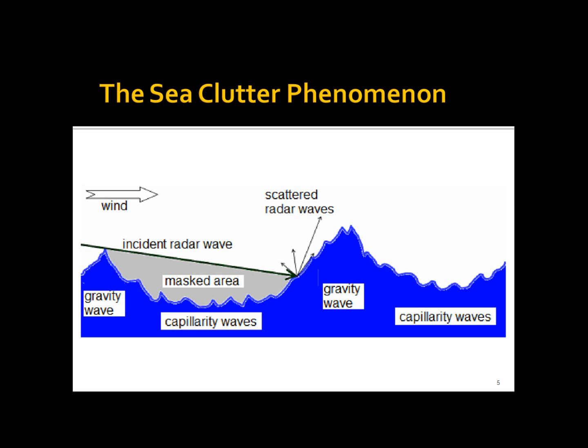As for the first approach, which relies on modeling the clutter and filtering it, we were focused in three models. The first is a one-dimensional stochastic model, which is an extension of the classical approach. It relies on the phenomenological model of the dynamics of the sea, as can be seen in the following figure. Basically, two kinds of waves are encountered at the surface of the sea, generated by two different mechanisms: capillary waves and gravity waves. Capillary waves are generated by the influence of the wind and express the surface tension of the water, while gravity waves are mainly generated by the accumulation of gravitational forces and are the main energy carrying factor.